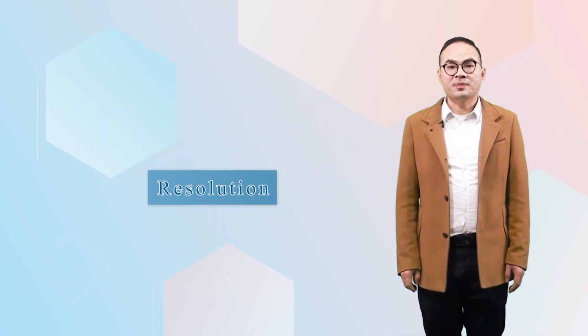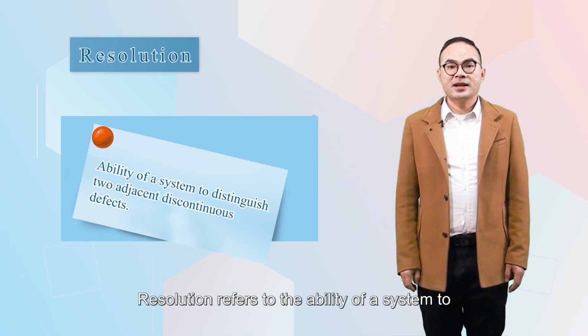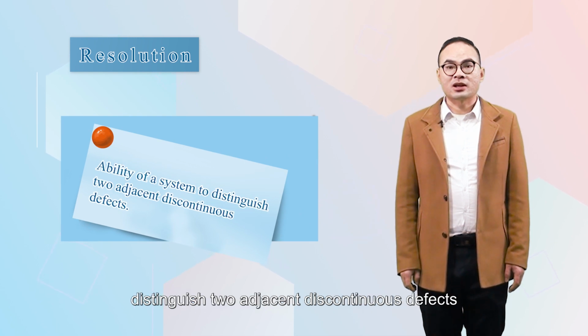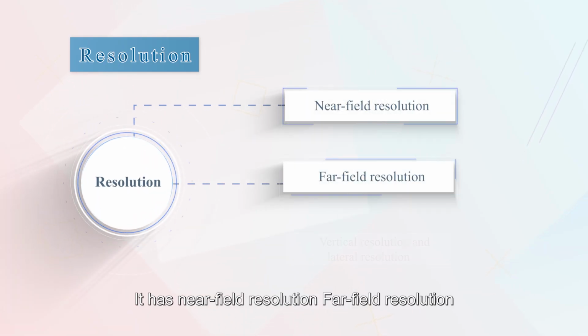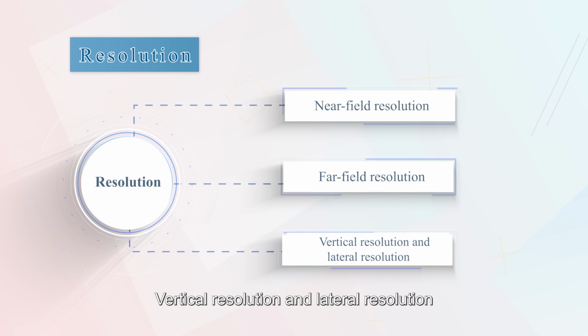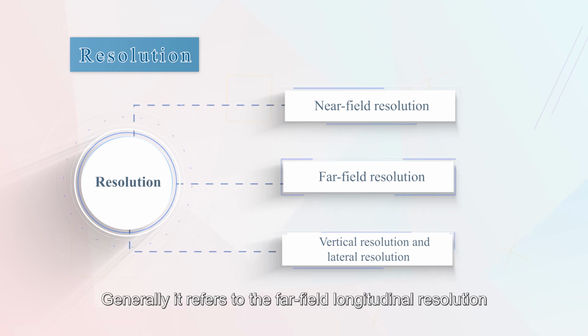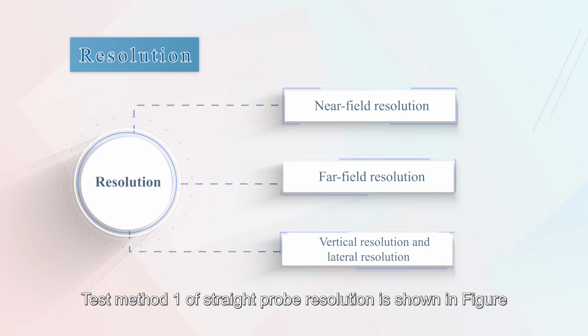Resolution. Resolution refers to the ability of a system to distinguish two adjacent continuous defects. It has near field resolution, far field resolution, vertical resolution, and lateral resolution. Generally, it refers to the far field longitudinal resolution. Test method 1 of straight probe resolution is shown in the figure.